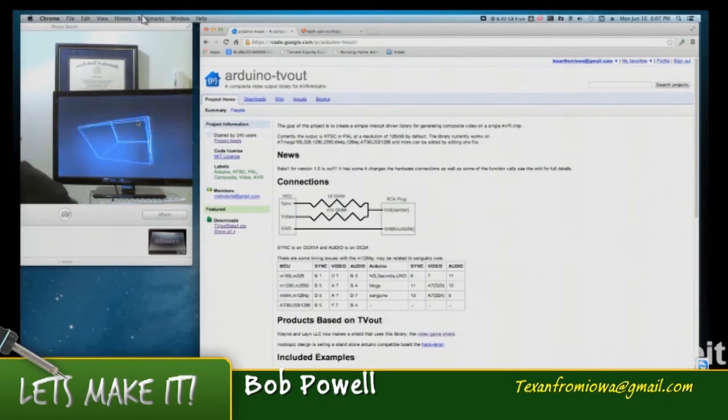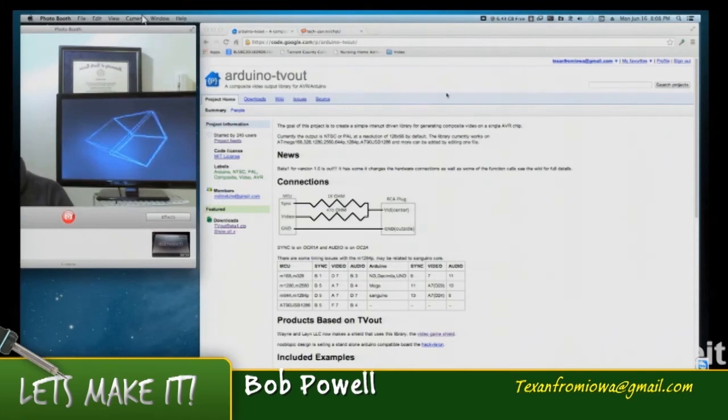And I had my multimeter out, I was checking resistance on the resistors, and finally found these two. I'm using a 976 ohm and a 454 ohm, and that gives me the ratio that I described. The irony is that this is within the 5%. I'm using 5% resistors, and it is within the 5%. So it's annoyingly difficult to find the right combination, but they are there.